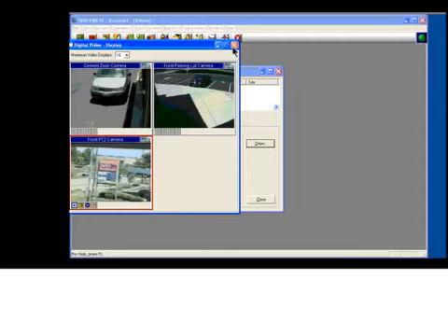Okay, so as far as troubleshooting goes, we verified that our software did work directly through the RapidEye. Verified our cameras work directly through the RapidEye. Now we're verifying that our cameras work directly through here. The next step is actually tying it all together. When a card is used or when a door is forced open, I want that video to pop up. How do we make that happen? And that's the next part that we're going to be covering.